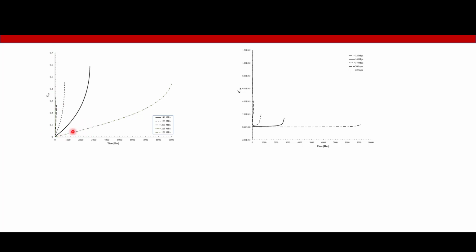So what you observe here is that at a very small value of stress, you can't make it out from here, but probably there is a primary creep zone, and then there is a linear strain increment with time, and then it becomes exponentially high. This exponential behavior increases as you go up with the stress. Okay, and this data comes from a conventional creep test, so there is no crack there. And then you calculate the strain rate and plot it versus time, and this is how it looks.